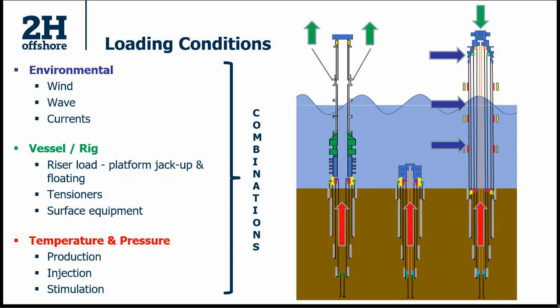The vessel and rig itself, there's a riser load that's applied to the well. Even a platform and a jack-up, a floating rig, they all have riser sections. There's always a stack up on top of the well in certain phases. The well might be supported by tensioners. There's direct loading on the top from surface equipment. And then we've got the operations that are ongoing in the well itself.